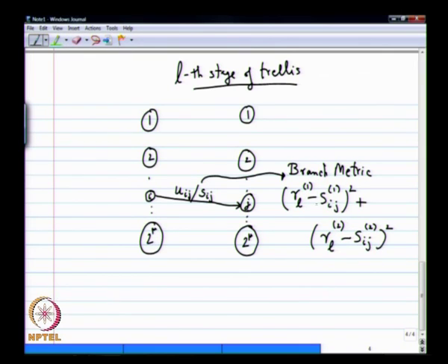Okay, and why did I define it this way? Right. So yeah, I am trying to minimize the sum of terms like this over all possible code words. So, if I have a code word on which this branch was actually used, this will be a term that will participate in the summation. Okay, so that is the idea. So, I am trying to write down all those summation terms in terms of the branches. Okay, so I think that is the first step. Okay, so we have some kind of a branch metric we can deal with. Is that okay? All right.